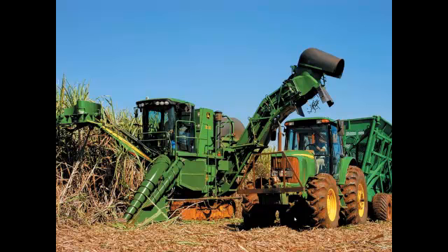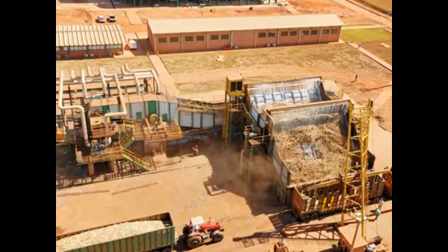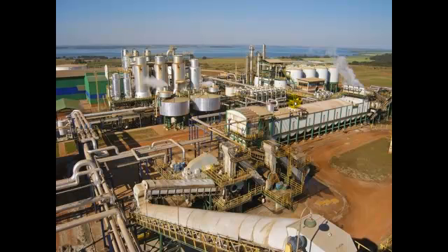Okay, just some pictures to give you an idea of the overall process. The harvesting machines, those wagons unload the sugarcane into feeders, and it is sent to a mechanical processing. Sugarcane is chopped, is washed, the trash is separated from the stalks, and so on. Then it goes to some equipment to extract the juice, which contains the sucrose. In this case, a 500 tons per hour diffuser. The juice is collected here in these beans, and it is sent to the fermentation process or to the sugar factory. Okay, the bagasse comes out here and it's sent to the boiler. It is burned there, and high pressure steam is produced, and it's used to heat wherever it's needed in the process, and also to generate